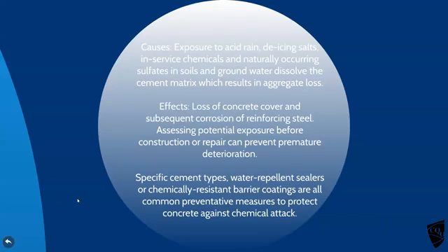You get some carbonation going on, so you get exposure to acid rain, or you can have de-icing salts. You know, in Northern European countries and America, they put salt on the roads when it's snowy and icy. You can spill chemicals. There's naturally occurring sulfates in soils and groundwater. They all expose your concrete.